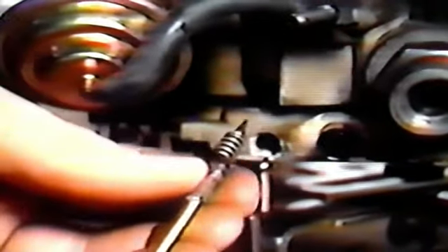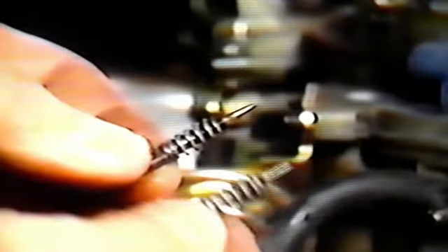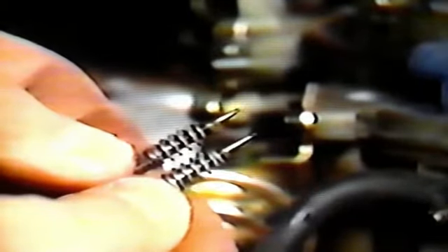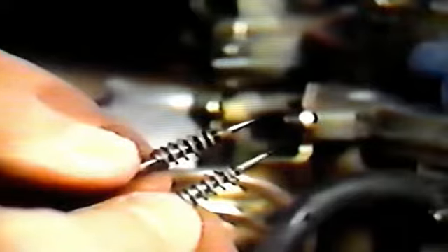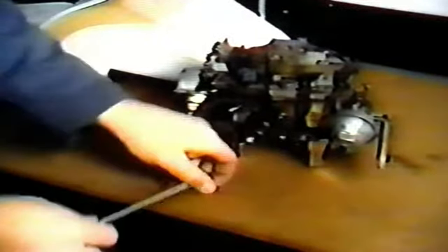After noting where the mixture screws were set, you want to remove them completely, check for any damage, and make certain the tapers match. Mixture screws may have a short, fat taper or a long, thin one. Be sure that the screws match. We've found instances where they do not. Assuming the screws are in good shape, you can return them to the carburetor and tighten until they are lightly seated. You then want to set them to factory specs. This information is provided in the shop manual.